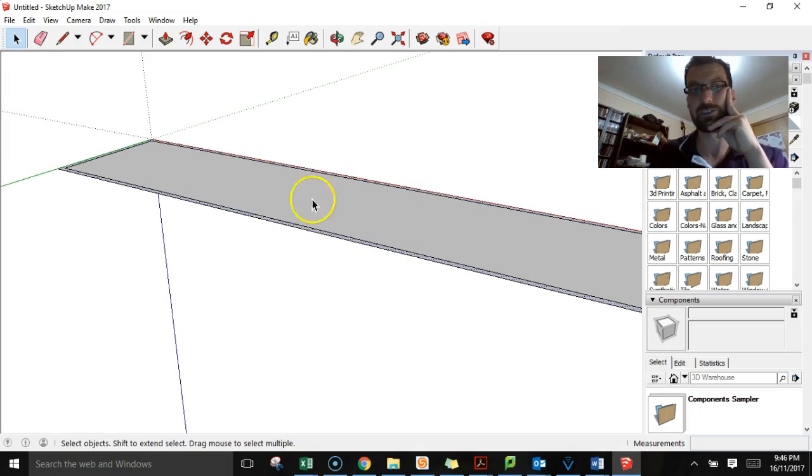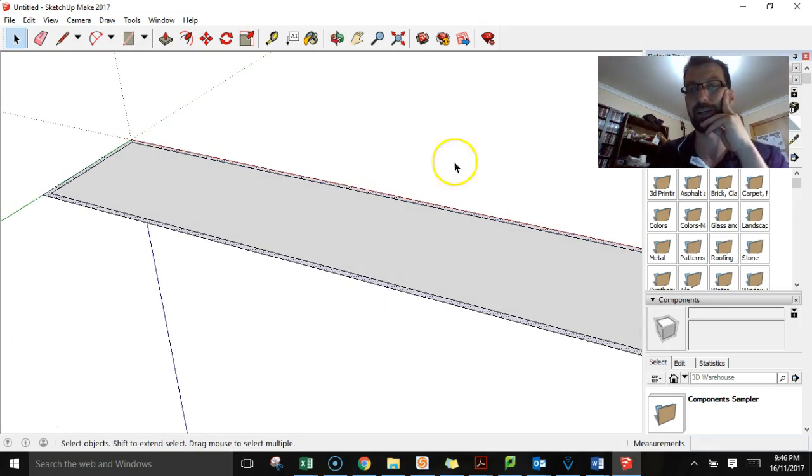So I've got 2 things, and what I can actually do, I'll show you this. I've actually got another wall to create. You should create all the walls first. It's much easier to do it like that than create another one, because all the walls are in theory the same height, so they're all actually part of the same thing.